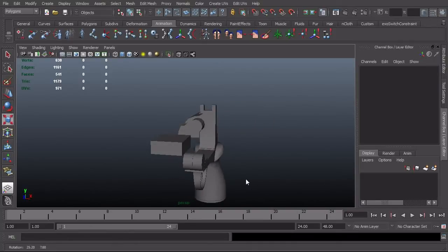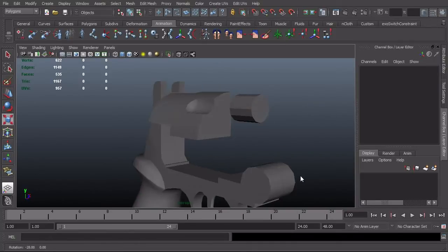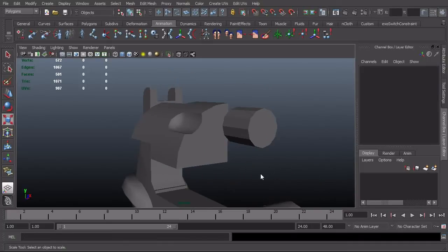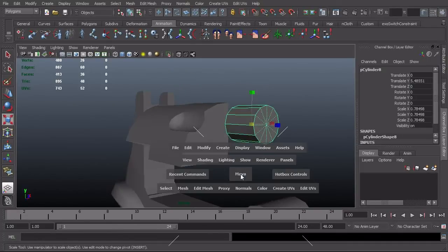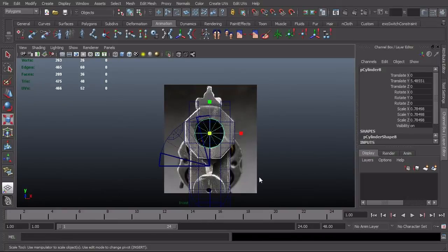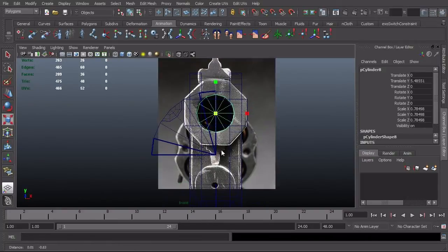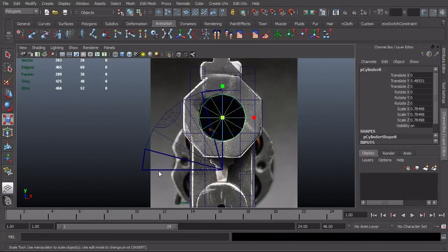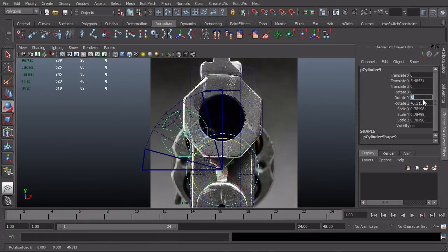So if we're only ever going to see it from that distance, I think that actually looks pretty good. So we'll go with 12 on this. And one thing I'll need to do is create a duplicate of that. Since I'm just working on a quarter of this, I need the other half of that cutout to be down here. So one easy way would be just to duplicate that, Command D, and then D and V, snap that pivot point down here, and then just rotate that down 90 degrees.